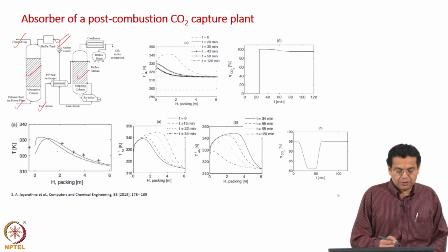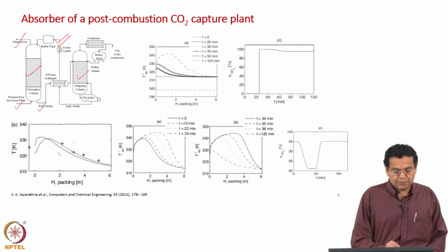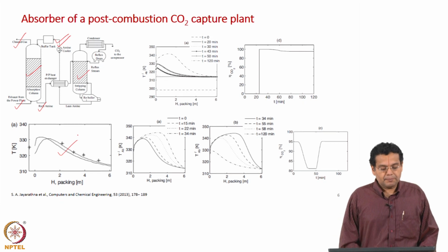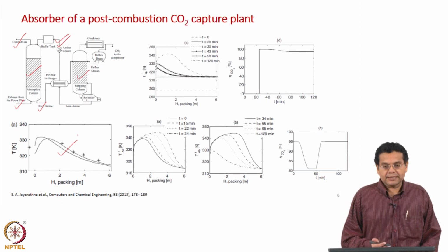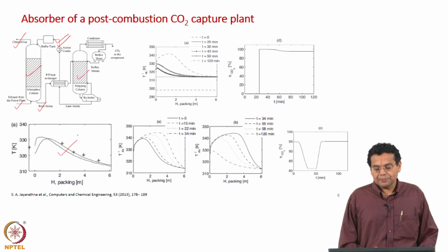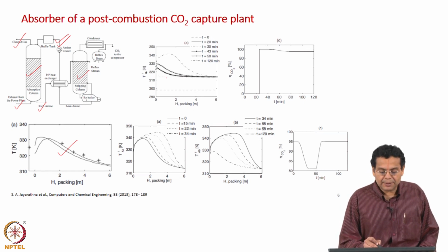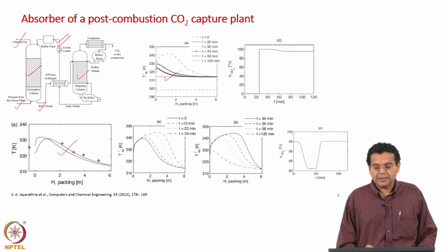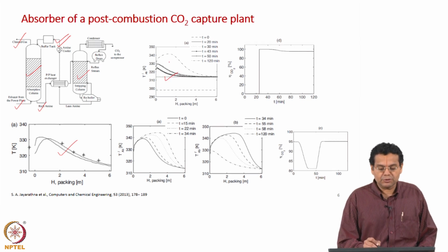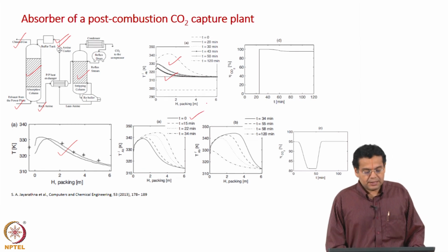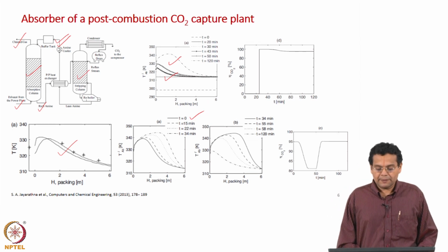the equations have been solved and the temperature profile along the length of the packed column is predicted and compared with experimental data. Not alone that, in this work they also study how the temperature varies along the length of the column under transient conditions. What happens when you start the plant, what happens when you give a change in gas flow rate or liquid flow rate, and the authors predict how the liquid phase temperature will vary along the length of the column at